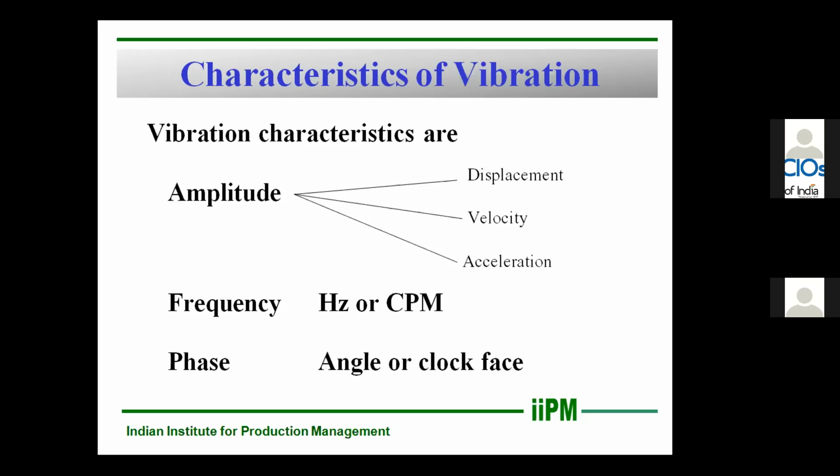Then next comes frequency. Frequency is nothing but the number of oscillations per second. So what is frequency and how is it going to help? Frequency will tell us the source of vibration, whether it is coming from the motor, the shaft, the gearbox, or the bearing. So it will tell us where the vibration is coming from.